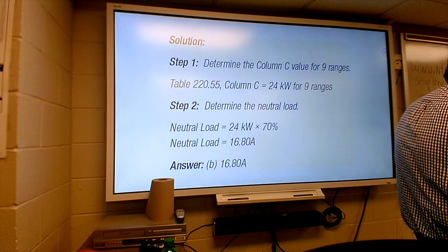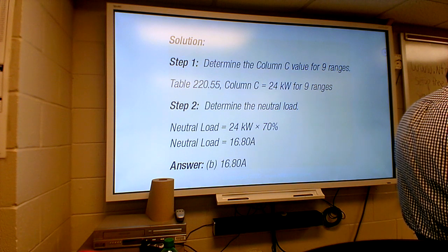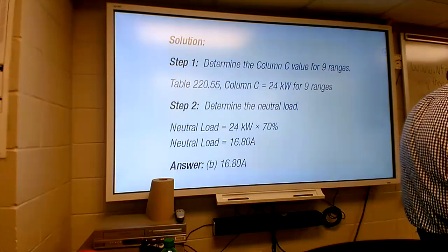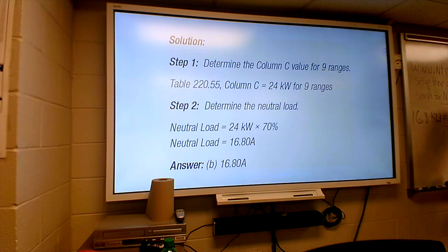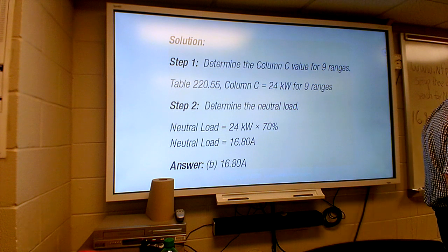Oh yeah, that's right. It's a 4 AWG for neutral. So it would be a number 4 AWG wire. Everybody okay with that? That would be the neutral wire.